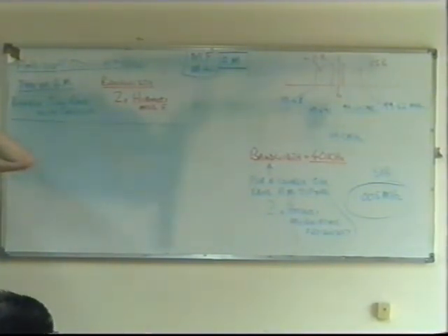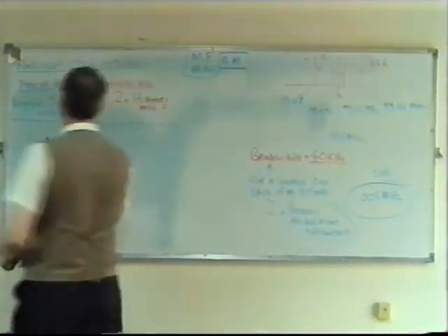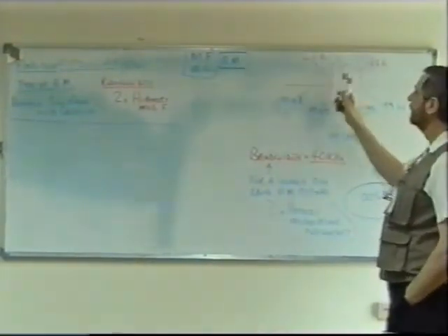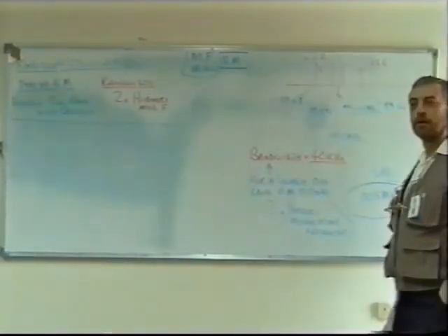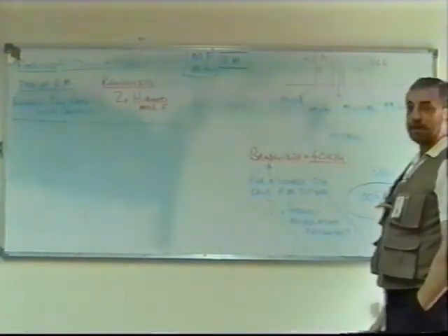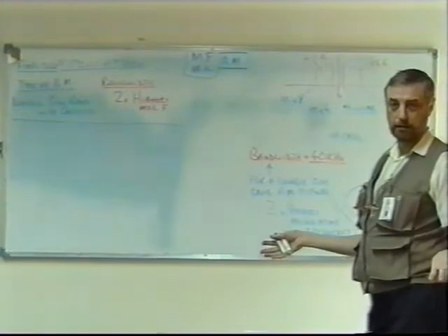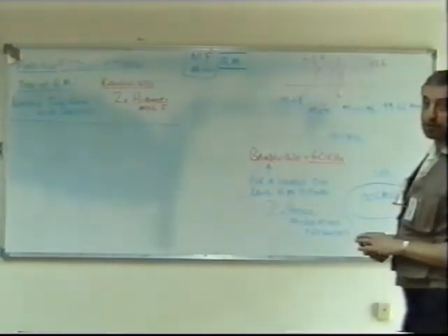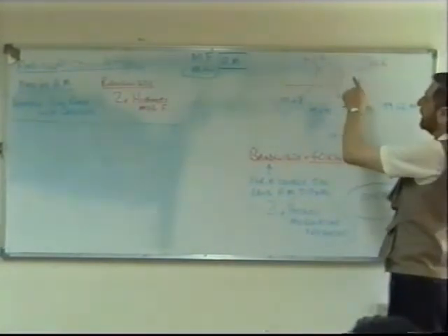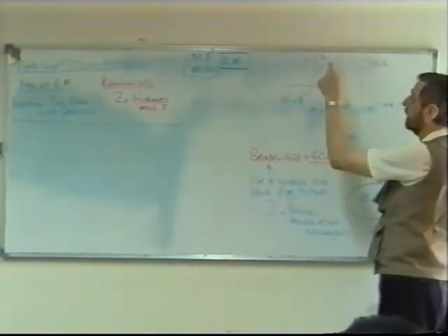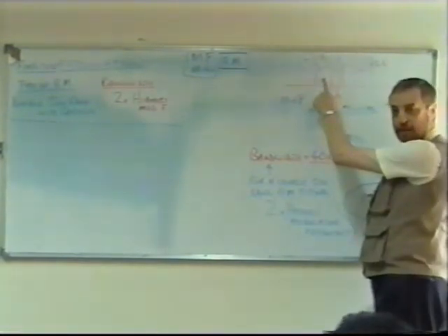Okay? A couple of other types of amplitude modulation. It is actually possible. Have a look at this signal. We've got an upper sideband and a lower sideband. Now, remember what we said, that all the information is contained within the sidebands. It so happens with amplitude modulation like this that the information in the upper sideband is exactly the same as the information in the lower sideband.